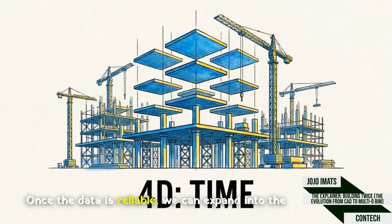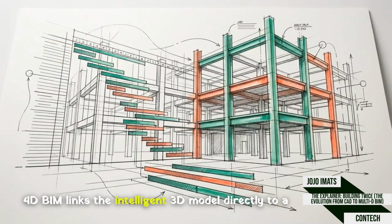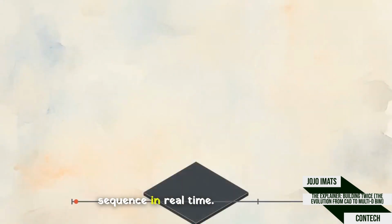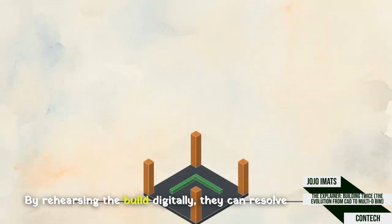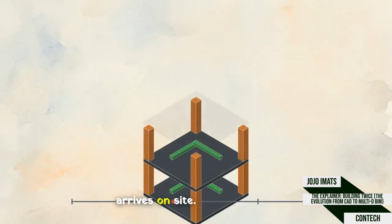Once the data is reliable, we can expand into the fourth dimension. 4D BIM links the intelligent 3D model directly to a project time schedule. This allows teams to simulate the construction sequence in real time. By rehearsing the build digitally, they can resolve logistical bottlenecks before heavy machinery arrives on site.